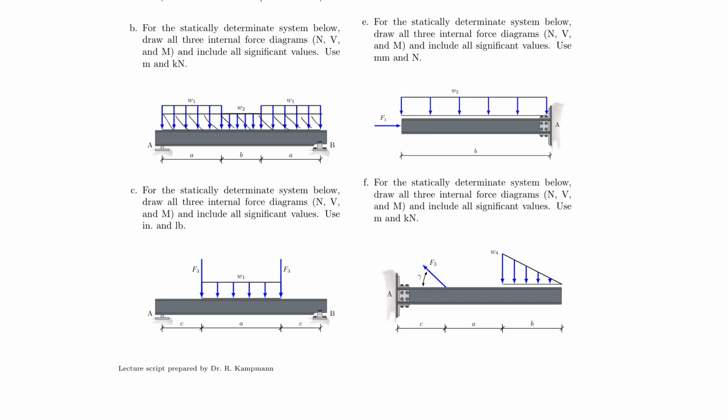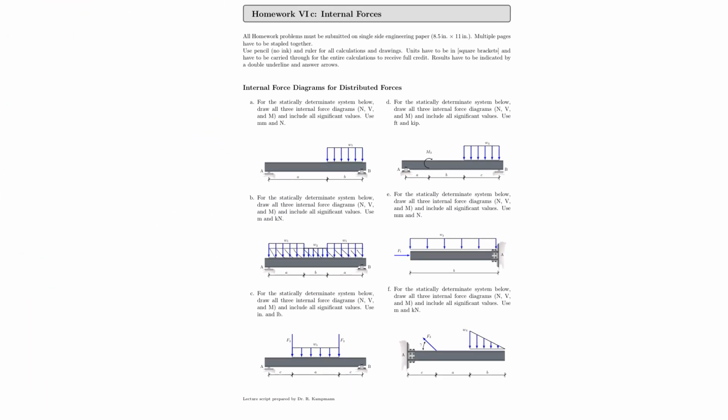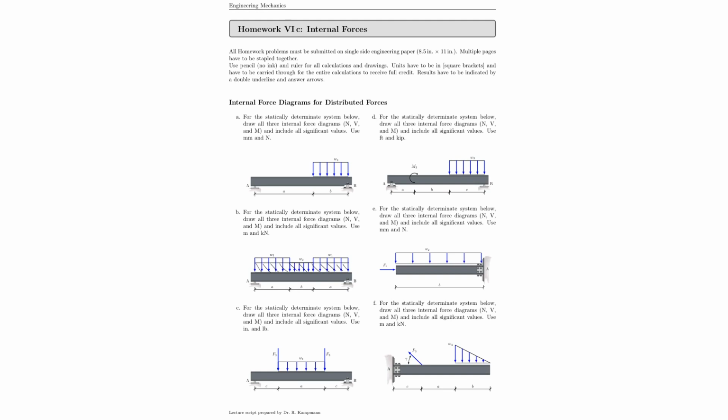If any of these problems really causes some trouble or you have a challenging time with these, that is not a problem. In fact, that's why we're doing it. We want to be challenged in our homework and not in our exams or in the real world. But if that is the case, please go ahead and just split up your beam into more cuts. For example, if this beam had a length of 10 meters, I would probably make a cut at 2 meters, at 4 meters, 6 meters, 8 meters, and 10 meters, just to give myself enough exposure to these cuts and to connect the dots properly.